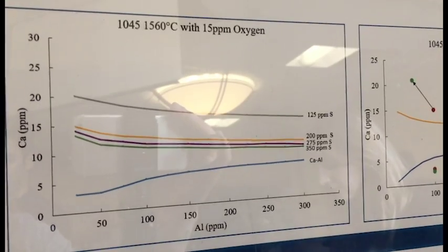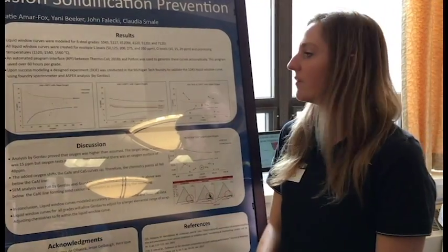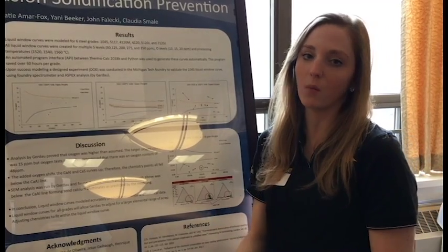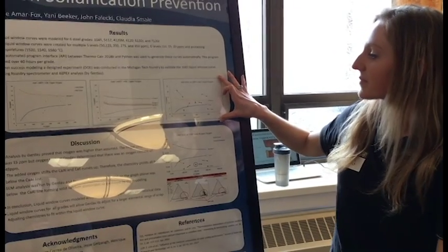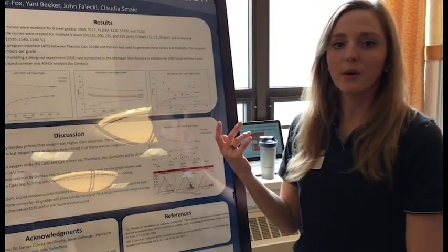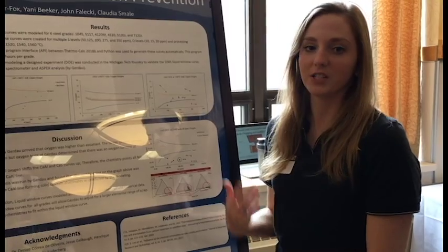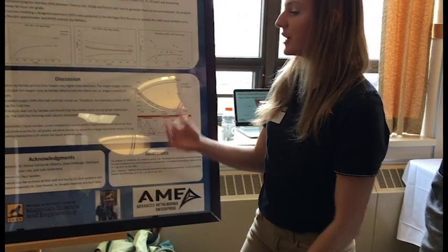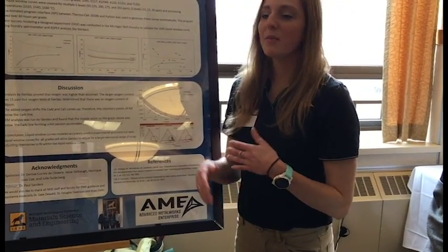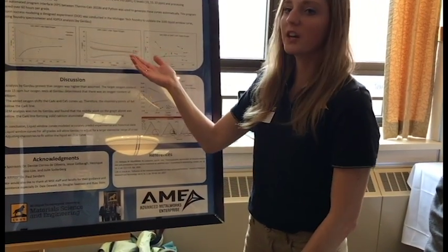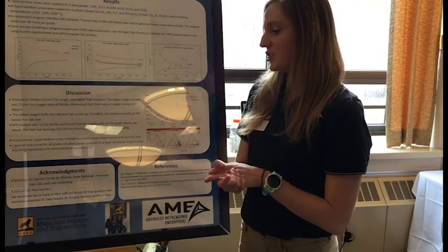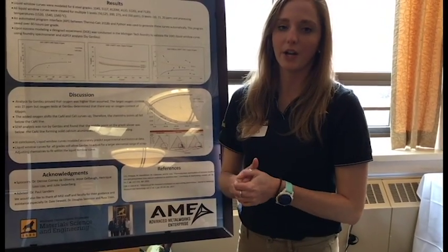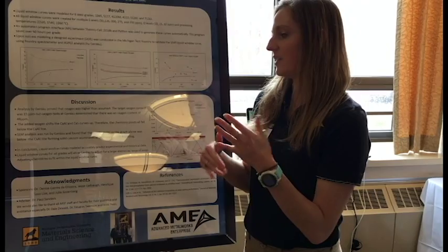This is what a typical curve looks like, so they have various software levels depending on what heat they're melting. And then further, to test our own steel in our foundry, we made a DOE with points of chemistries that we wanted to aim and target to hit. Gerdau uses all scrap metal, and by creating these liquid window curves, it allows them to buy a wider range of elemental compositions, because they can adjust throughout and know what points to hit throughout the curve.